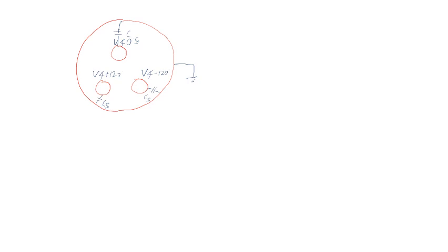There is another capacitance, that is between two cores. Between two cores there will be a capacitance CC. So to calculate the overall capacitance, we need to calculate two different capacitances: the core-sheath capacitance and the CC, between two cores.